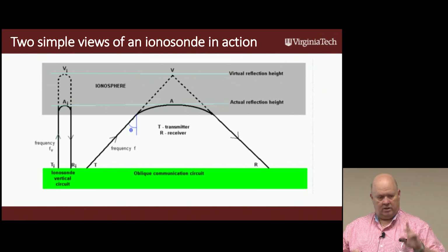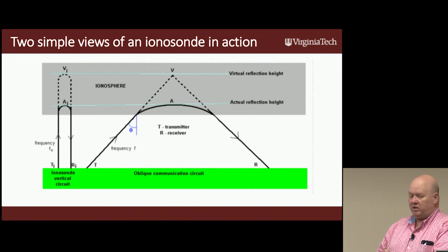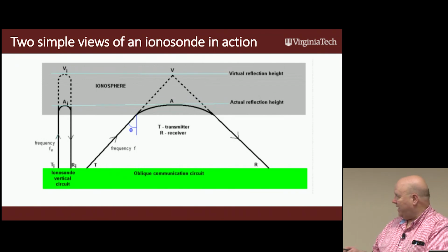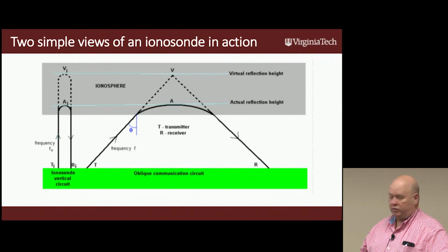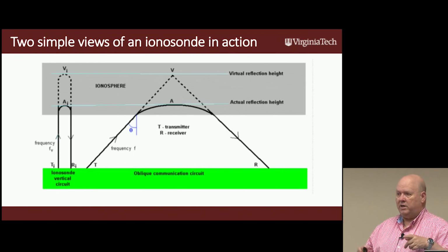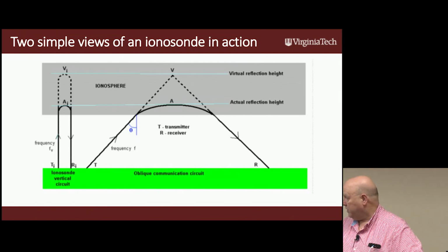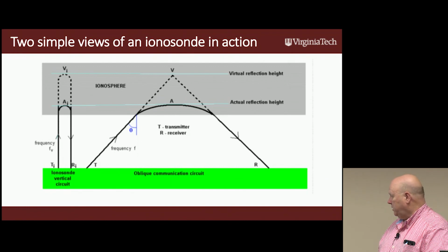Literally, it's send out a pulse, correlate for the signal coming back, and measure the interval in samples between the transmitted pulse and the received pulse. Because of the speed of light, that tells you the up and down time. So 2 times the height of the ionosphere is the number of samples divided by the sample rate in seconds, the amount of time it took, and thus the height of the ionosphere. We did this before the eclipse, and we're continuing to add to it.